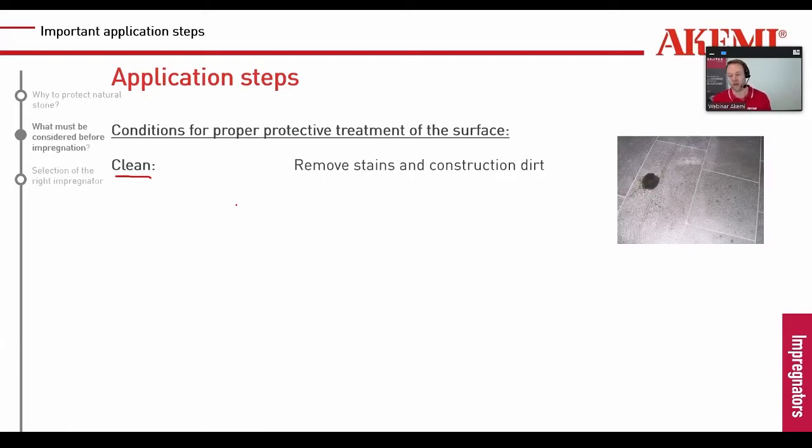So in this case here on the right side, we have to remove the dirt. Here I would use some oil remover or some concrete film remover to remove these residues of grout material. Then the second case, it must be stain-free.